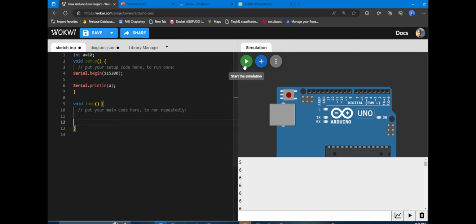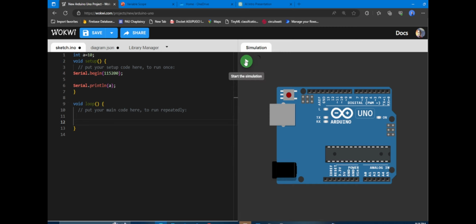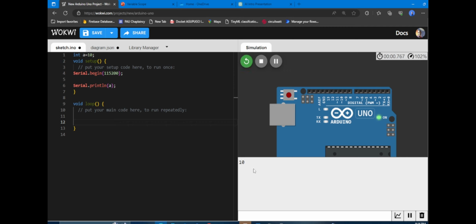Now normally it's not inside void setup, but it's going to see it because now A is global, so A is 10. The same thing happens when I put it in the void loop. I'm going to print 10 continuously, because now the void loop and void setup can also see it, because it's in global scope. This also means I can change this variable from any point in my code. I can change it here, A equals 5.